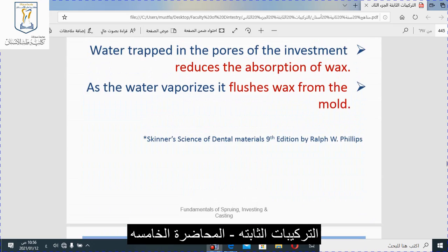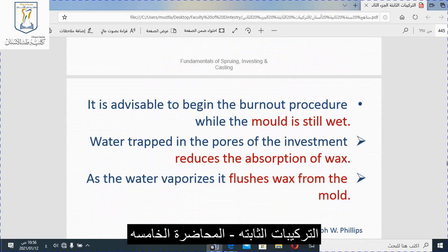Melting, and this is important, you know. So we have to cold mold to prevent the wax from obstructing or filling the porosity, or filling the fins, the area through which the air will be relieved. So we know we need the area, either the fins or porosity, to leave the mold, to give the space for the alloy.